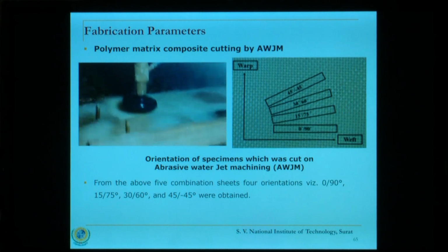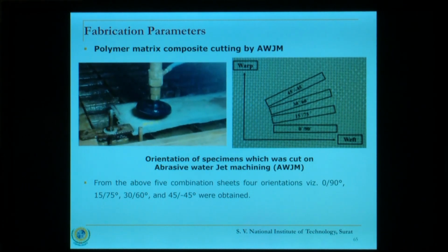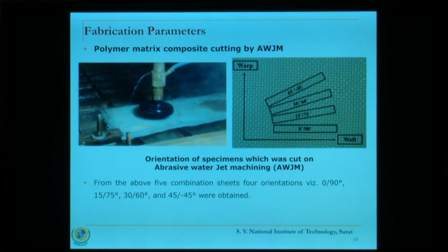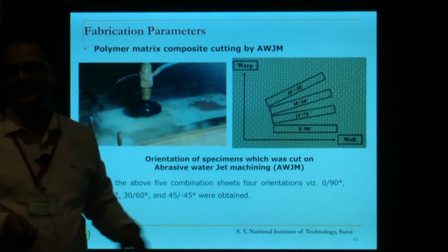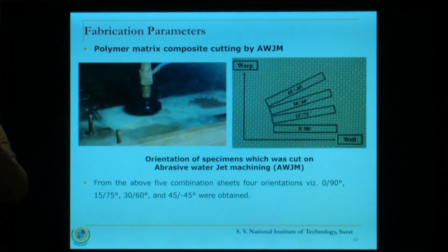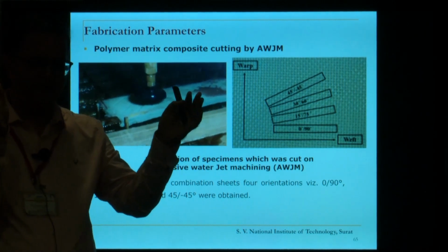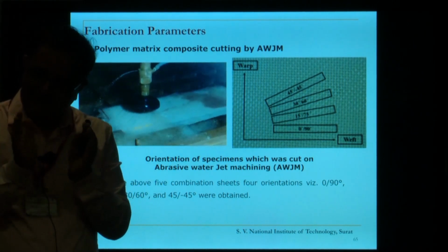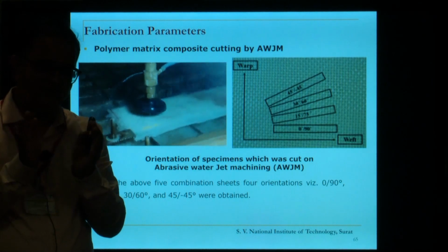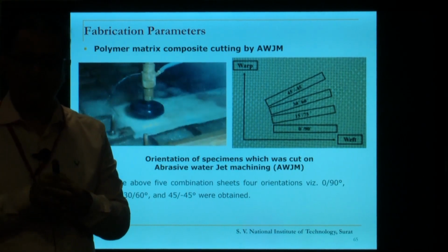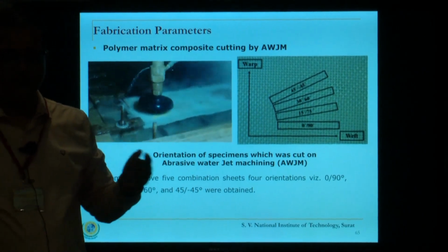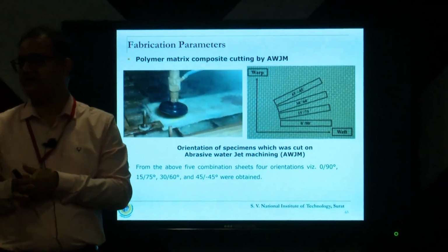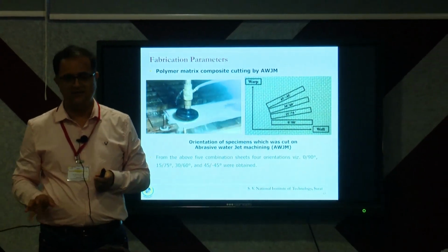This is not strip layout, but how to have maximum utilization of the part, and how many maximum samples you can get. For tensile, as per ASTM standard, there is a certain length. For impact, the length is small. For flexural, it is somewhere in between. So on a single fabric, you may go for multiple positions and get multiple parts, for maximum utilization.